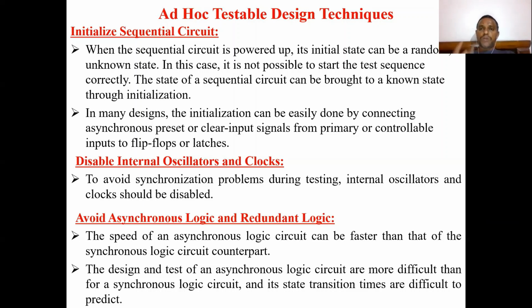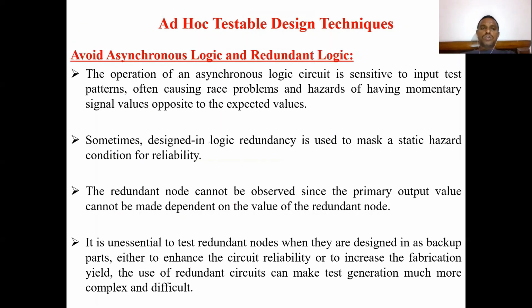The only reason is that asynchronous circuits are very speedy. So what do we have to do? The operation of an asynchronous logic circuit is sensitive to the input test patterns, often causing race problems and hazards of having momentary signal values opposite to the expected values.